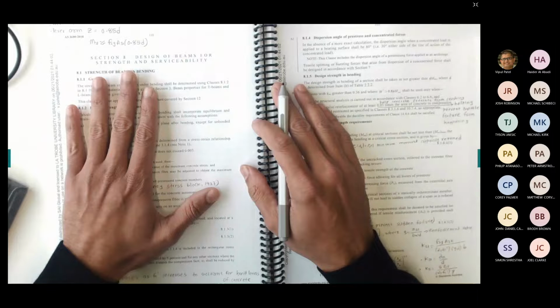So this one is the neutral axis, the depth of the neutral axis, that will divide your concrete beam into 2 zones. Above the neutral axis is the compression zone, below the neutral axis is the tension zone. So that is the depth of the neutral axis and that is denoted by dn. Let me put the neutral axis here.